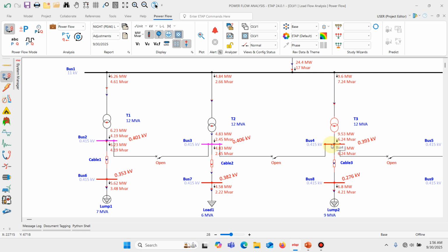Now, of course, this is just a quick glimpse of ETAP software. In our professional training, we cover different load flow analysis methods such as the Newton-Raphson, the adaptive Newton-Raphson, the fast decoupled, and the likes. We also cover how to input realistic load models, and also ETAP has this feature that can allow you to generate a detailed and comprehensive output report. So we are going to be teaching you how to generate that and how to interpret the results in details,